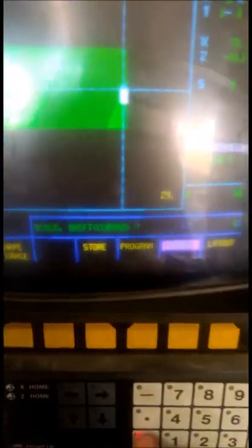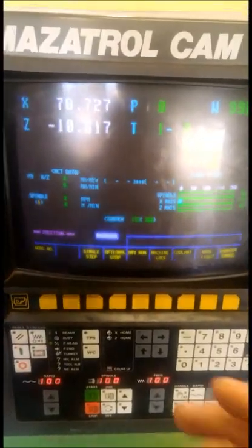So I could set that at say 60mm. Then when we bring up the workpiece figure, see it's much smaller now. Or I could zoom in there and set that at 15. And now we're much closer on it, so we can actually see it a little bit better. So that's about all there is for setup.